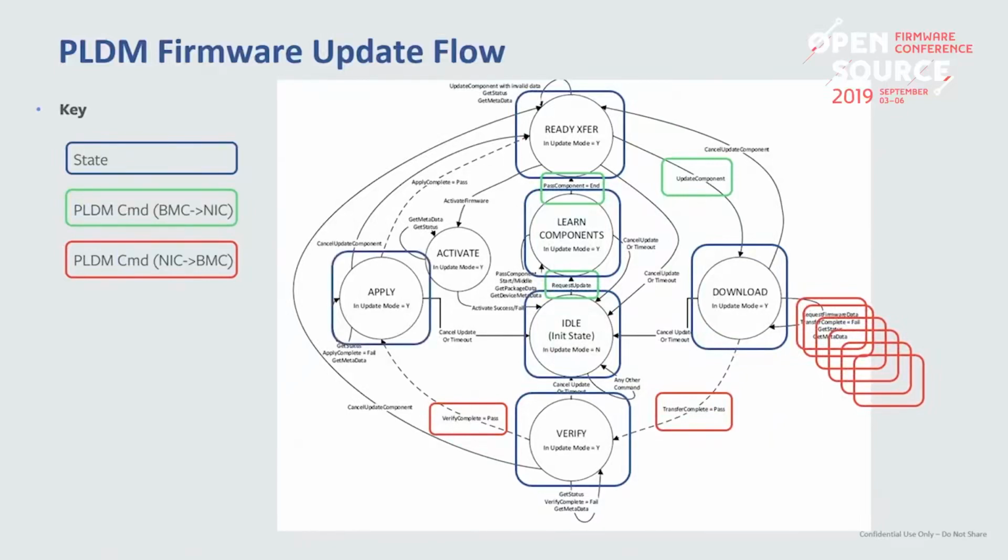Apply actually doesn't mean activate. Here you'll see 2 different states: there's apply and there's activation. Apply is implementation dependent. It can be a no-op on the device side, but essentially what this tells the BMC is this firmware has been verified and we are good to go. But it doesn't mean it's been activated yet.